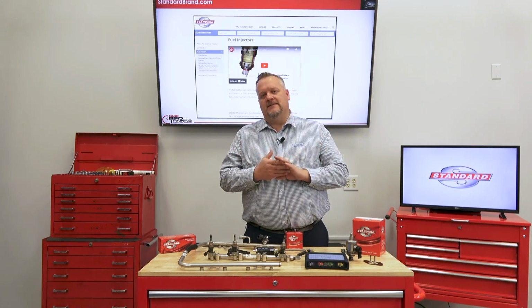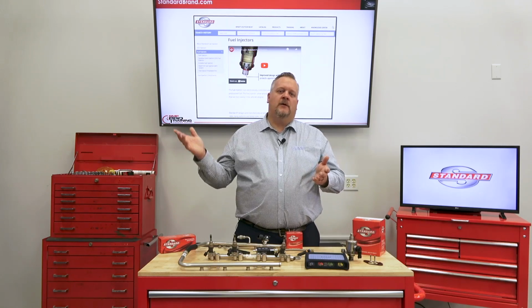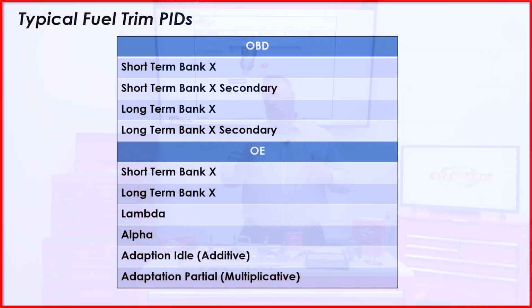Well, a lot of it depends on the manufacturer. If you're struggling with some of those and you're confused about them, again, I recommend you exit out of the OE side of the scan tool and go back to the generic side and look at generic OBD information, which is standardized. It's the same information you've been looking at for years, and it can help you out with some of that. And that looks like the bulk of the questions for now, Ryan.